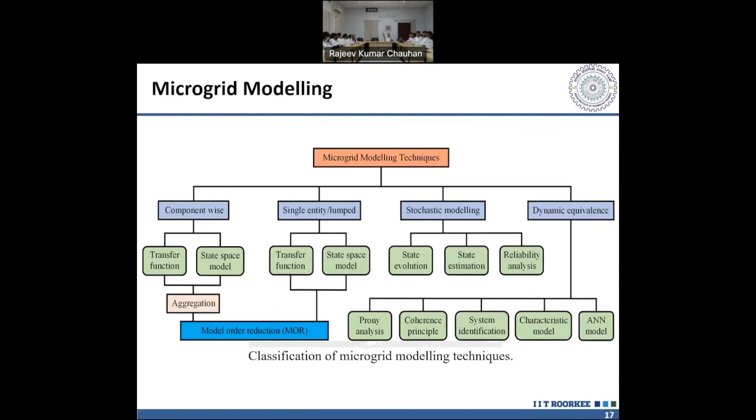If you neglect the inductance, like in a DC machine course, you write the equation V equals E plus IR. In control, we write the equation V equals E, the back EMF, plus IR plus L di by dt.